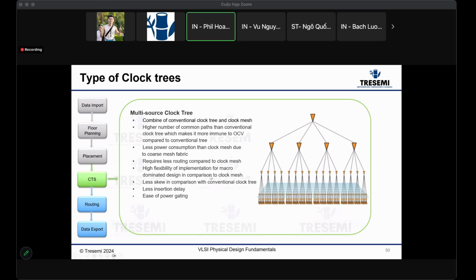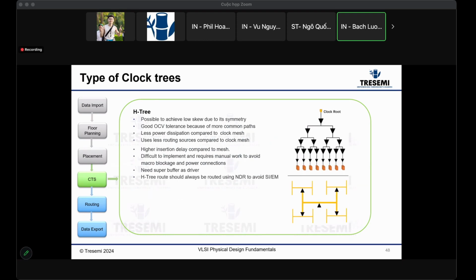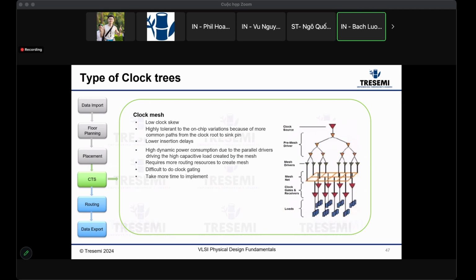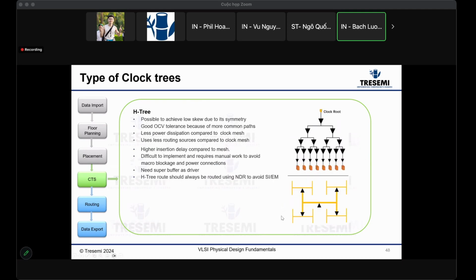What did you choose for the last 3nm design that you taped out recently, and why? We built a combination of mesh and H3. We have these big spines and we put some buffers in between. It's not quite H3, it's a combination of the two. We had a mesh that distributed the clock throughout, and then we had this super spine clock tree on the top layer metals, with super buffers spacing them evenly to balance out. So we did a combination of the two.